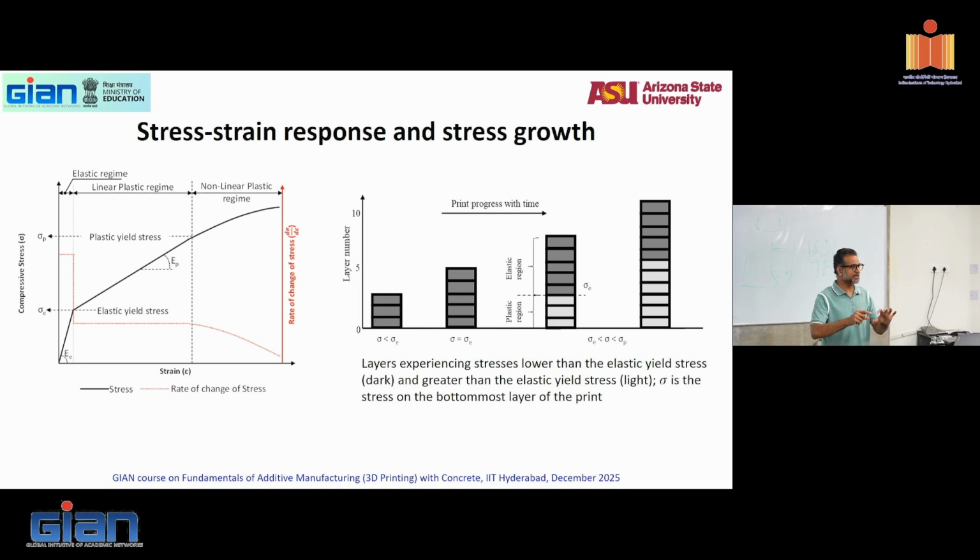So to print 6 layers, and very, very carefully using a very sharp cylindrical pipe, slowly push through the material to extract a cylinder from that printed material. And then do a very, very slow loading of that material, extremely slow loading.